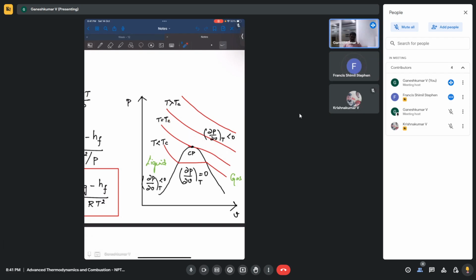Right. It's not like that. The liquid is there, and if you raise its temperature and pressure to that level, it doesn't require any additional energy to get converted into gas. It can automatically get converted to gas. So there is no latent heat, there is no hfg for the gas, right? Yes, sir, hfg goes to 0. So without any energy, I can convert this liquid to gas.